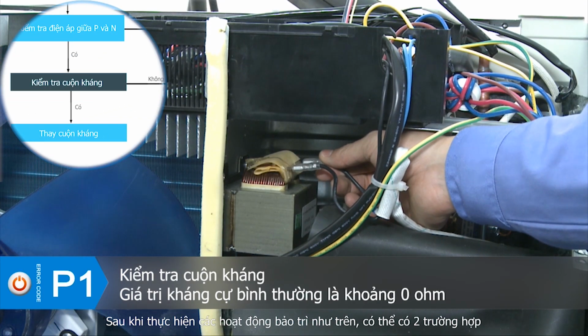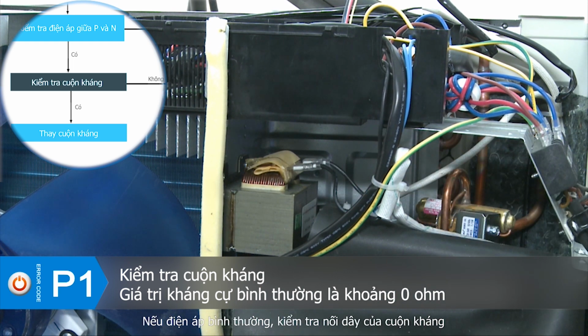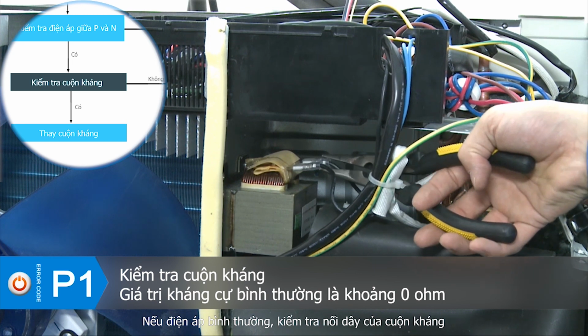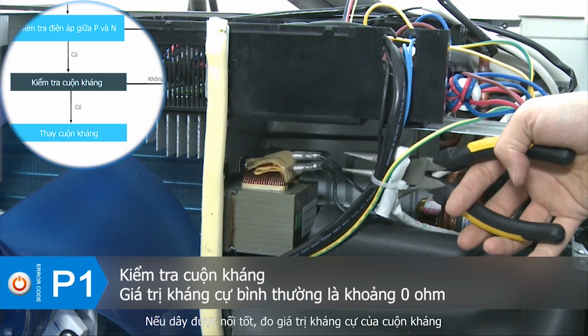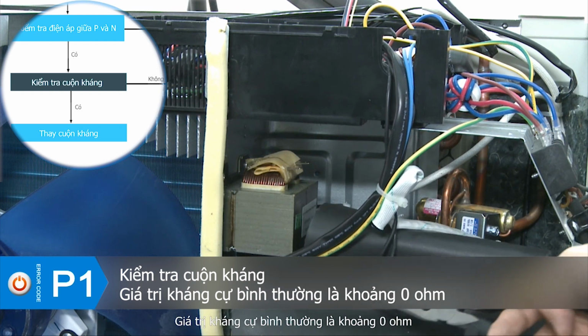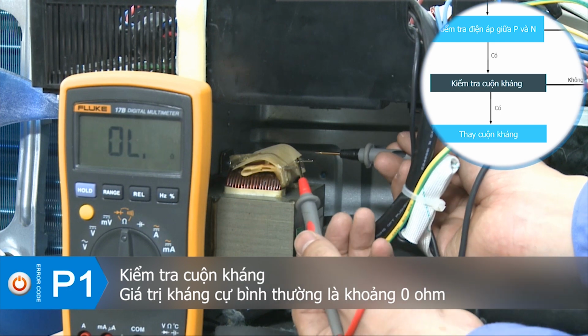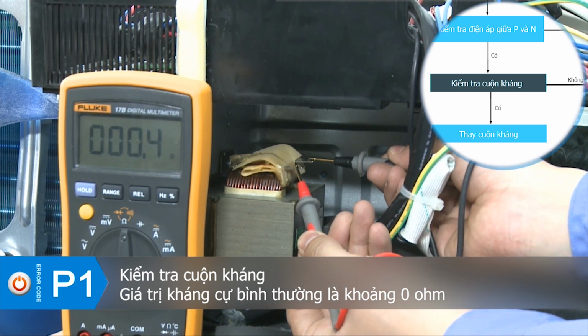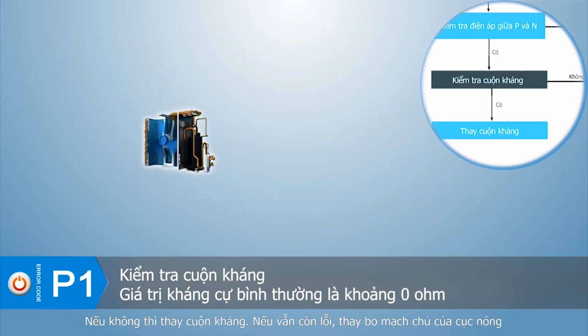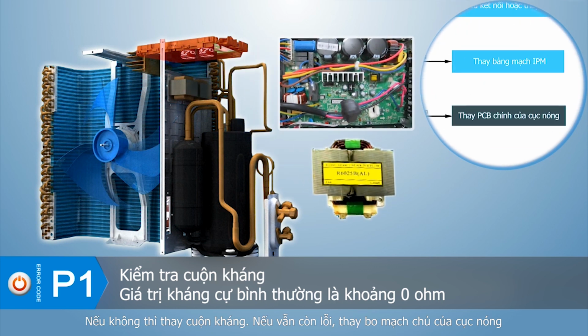After the maintenance above, there could be two cases. If the voltage is normal, check the wiring of the reactor. If the wire is well connected, measure the resistance value of the reactor. The normal resistance value should be around 0 ohms. If not, replace it with a new reactor. If the error still exists, replace the outdoor main board.